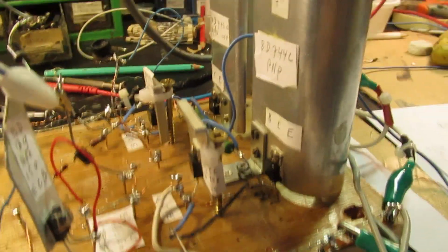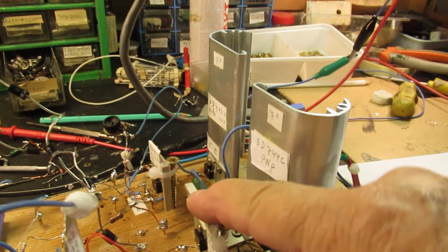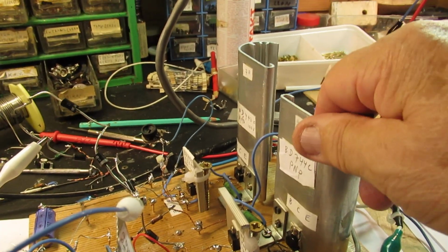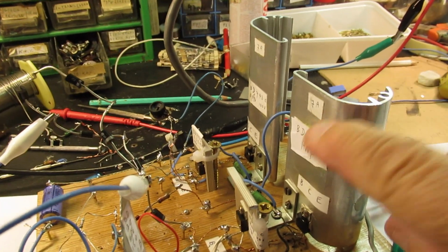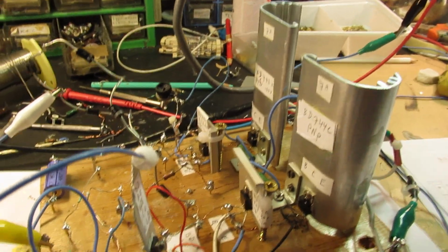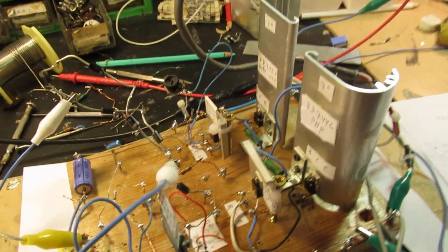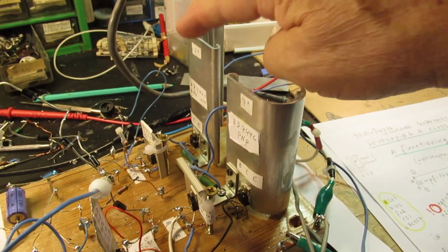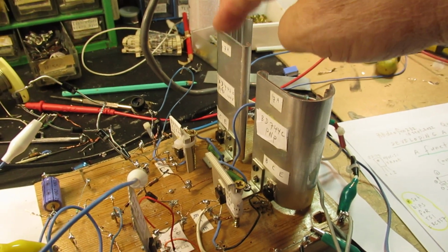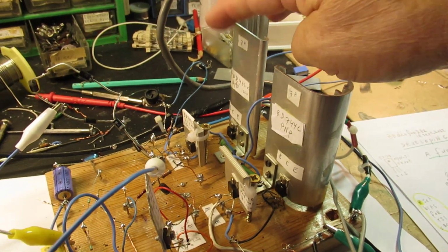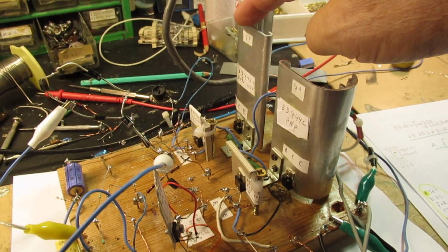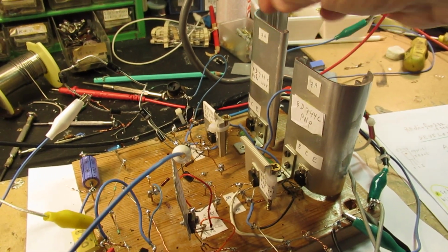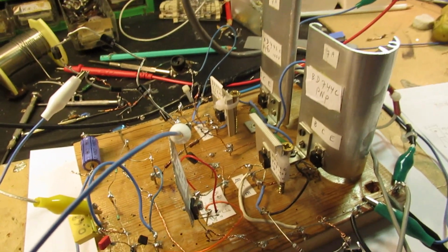In my earlier experiments the problem was that the driver transistors, the first transistors in the Darlington, got warm, but the end transistors did not get warm. They kept cool. That means that there is no current flowing. In such a circuit, both transistors must get equally warm. When they are not getting equally warm, you surely know that one transistor is not in the conducting stage, so it doesn't amplify when we are talking about audio. And now it's okay, everything works.